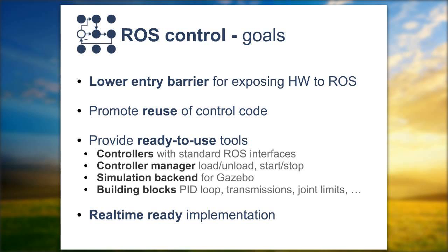Another important goal is to provide a set of ready-to-use tools, such as controllers that expose standard ROS interfaces, and a controller manager for handling the life cycle of a controller, such as loading it, starting it, stopping it, and unloading it. There is also a simulation backend for the Gazebo simulator, and a bunch of building blocks such as a PID loop, mechanical transmissions, joint limits, and so on.